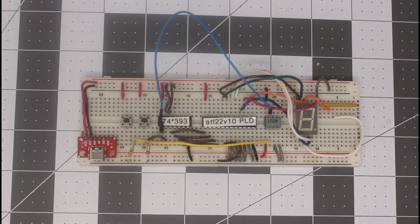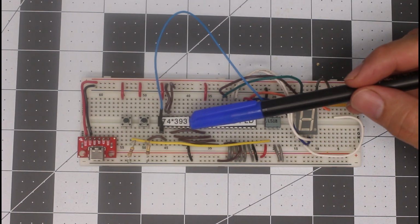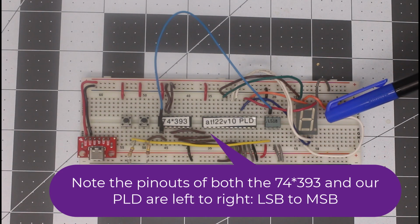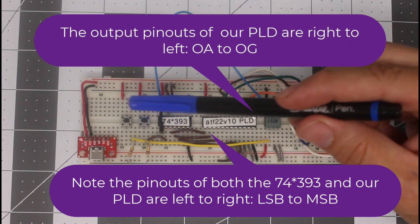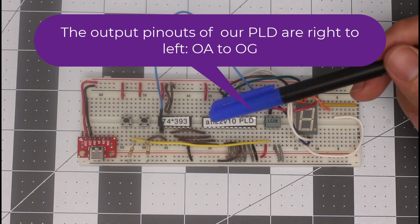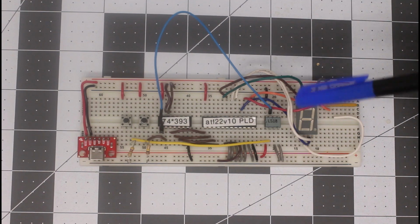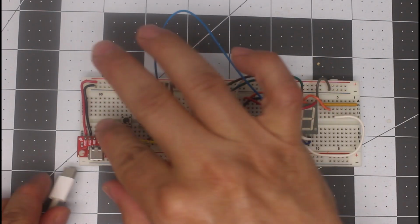The circuit consists of a 74393 4-bit counter, which is used as an input to our PLD. The output drives the 7-segment LED seen here. Additionally, I have 2 buttons, one to reset the 4-bit counter and one to increment the 4-bit counter, and an LS18 debounce IC to prevent double counting when I push the button. So let's go ahead and test it out.